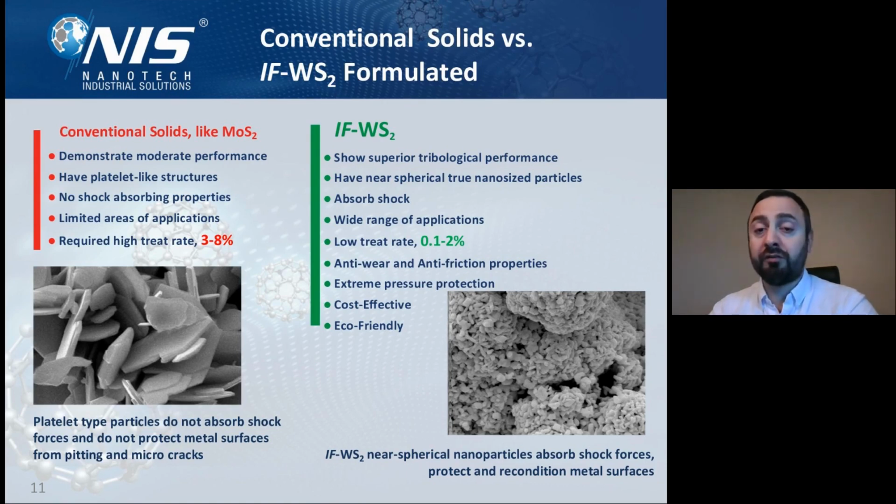They absorb shock, so they create a barrier for shock absorbance and prevent micropitting and crack propagation. They have very good anti-wear, anti-friction properties, and a much wider range of applications because IF-WS2 is supplied in liquid form, in dispersion form. I would like to mention that a dispersion is not a solution.